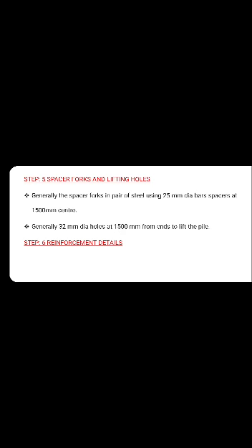Helical reinforcements are provided at a distance 3D, and for every 1500 mm we have to provide spacer forks, and a steel strap is also provided. These are provided to keep the pile sharp enough to get into the hard rock, and a steel shoe is provided, and also 32 mm dia holes are provided.